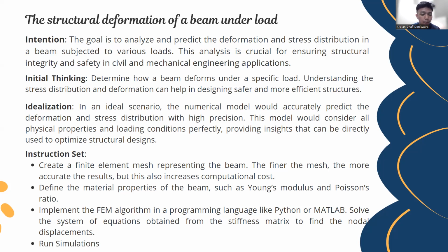The finer the mesh, the more accurate the results. But this also increases computational cost. And then we define the material properties of the beam, such as Young's modulus and Poisson's ratio. Then we implement the FEM algorithm in a programming language like Python or MATLAB. Solve the system of equations obtained from the stiffness matrix to find the nodal displacements. Then we run the simulations.